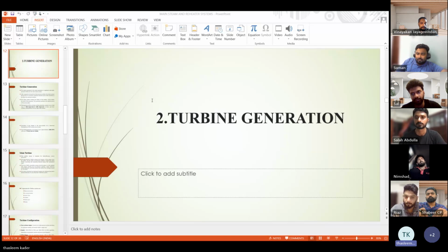Our colleague Mr. Sela already gave a detailed idea about the steam generator functions and importance. Now this steam is produced and goes directly to the high pressure turbine, which helps to expand the steam, and the pressure is reduced. It then goes directly to the MSR. What is MSR? MSR means moisture separator reheater.